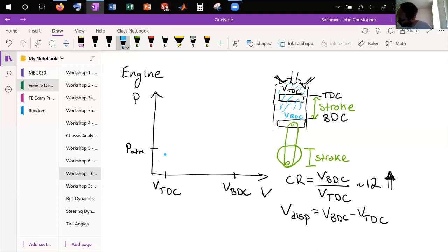And we usually will say this is 0 degrees crank angle, and that's when you're at your top dead center. You'll typically have sensors in your car these days to sense the crank angle position. But remember, you do 2 revolutions for every one of these phases of your engine. So you could use a cam sensor, because your cam will usually spin half as fast as your crank.